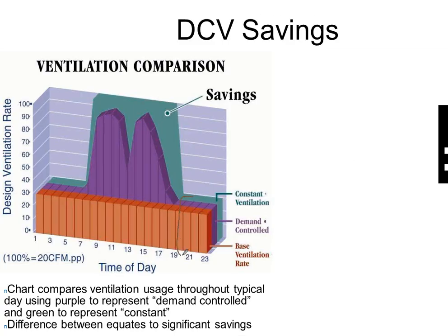These sections right here really could go down to 0. The reason it was shown like this is because what should happen is they should go down to 0, right? The green curve should drop all the way down to the bottom at 0. But what happens in a real building, like I said, is it goes up and down on heating and cooling call. So we left it at 30 on the drawing to represent what happens in a real building, right, of it being either 100% or 0% of ventilation air, depending on whether the stat's calling for heating or cooling or not, right? But that's what that was for.